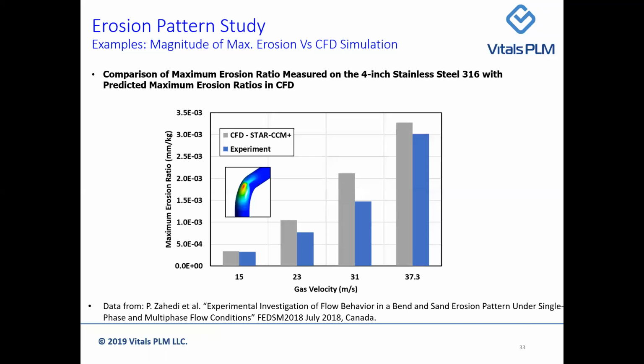How are the erosion models sensitive to the mesh, especially for the boundary layers? Yeah, erosion is actually sensitive to the thickness of the first layer mesh close to the wall. So we need to make sure our first layer thickness is fine enough to track particles all the way close to the wall. The recommended value for the first layer thickness is usually the particle diameter, to make sure the particle goes all the way through the first layer and captures the velocity that represents the particle impact velocity in the equations.